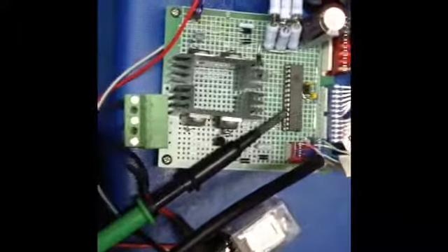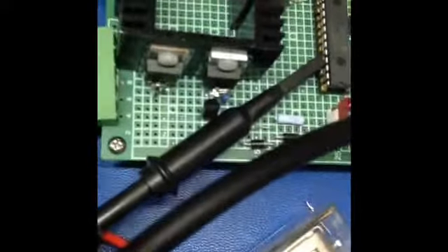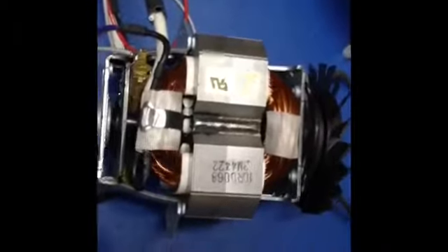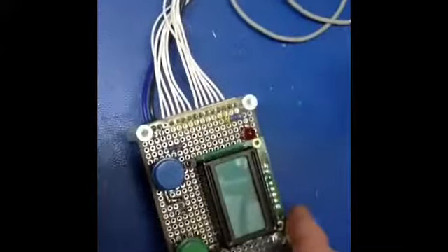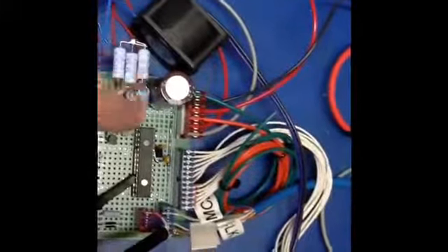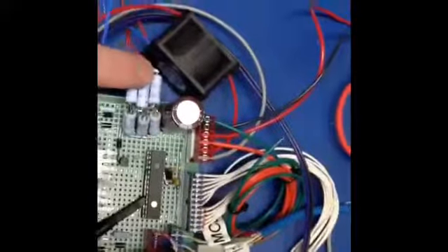And I will have another video showing the schematic for this. But in a nutshell, I've got a P and an N on either side of the bridge feeding my fancy little motor here, which is from a blender. I have got a dsPIC30 on there, and a little touch interface screen here that I'm still programming. I've got a linear regulator for the 5 volts with this sort of Frankenstein dropping resistor, and I've got a fan to keep it cold because I'm dropping quite a bit across a very small regulator.